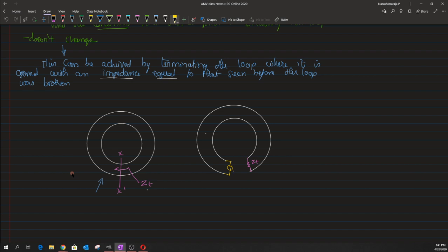Okay, and for that input source, I assume that this particular loop is basically a voltage feedback loop. The type of source that I am connecting at the input, towards the left side of the open feedback loop, is considered to be Vt. Now clearly, this signal Vt would then travel through this network along this particular path, and then it appears across the Zt as a voltage drop which is marked as Vr.